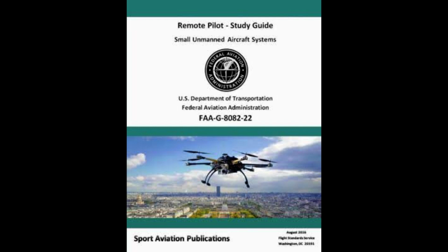1. Although a maximum gross takeoff weight may be specified, the aircraft may not always safely take off with this load under all conditions. Conditions that affect takeoff and climb performance, such as high elevations, high air temperatures, high humidity, and high-density altitudes, may require a reduction in weight before flight is attempted. Other factors to consider prior to takeoff are runway/launch area length, surface, slope, surface wind, and the presence of obstacles. These factors may require a reduction in weight prior to flight.